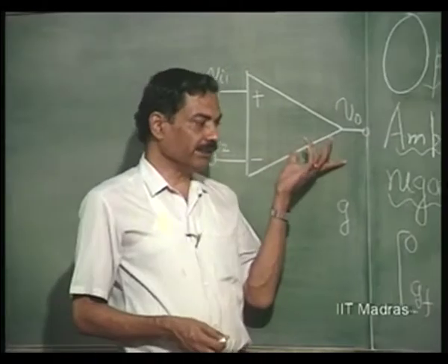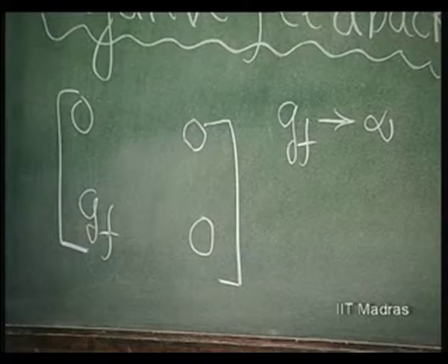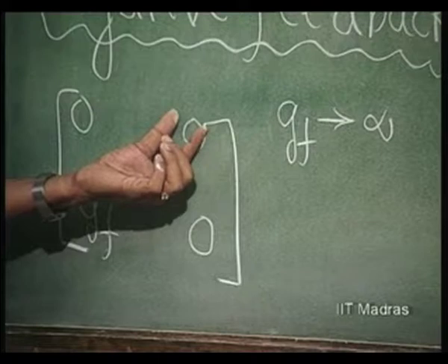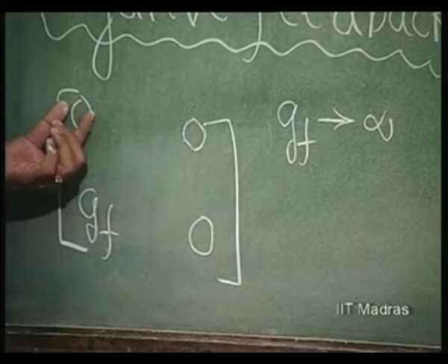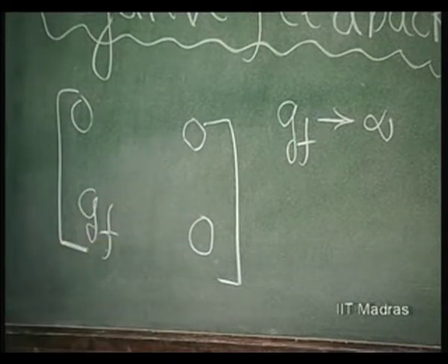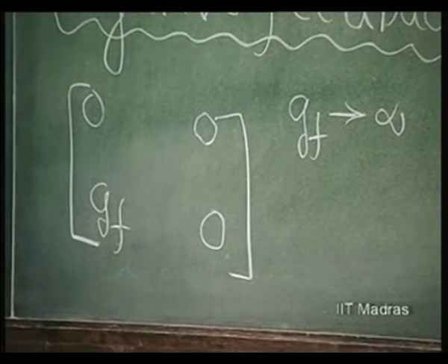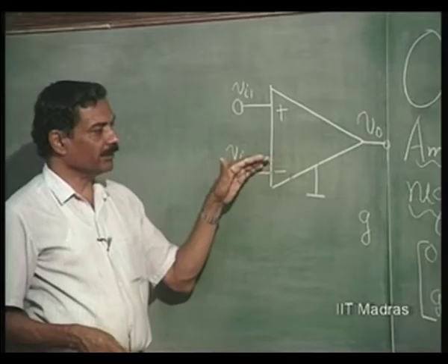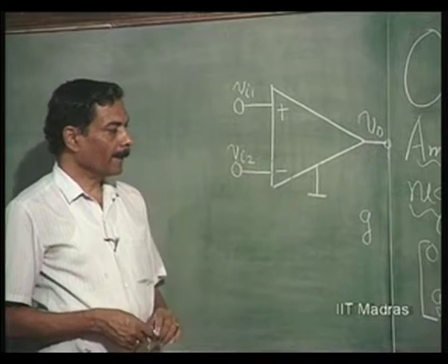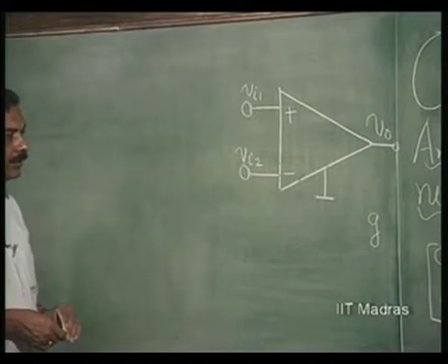So, in a cascaded version, please remember, this is the multiplication of the forward transfer parameters of the individual stages. So, it improves drastically, this keeps on coming down feedback, this is due to the input stage, this is due to the output stage. Anyway, we can design these things so that these represent operational voltage amplifier. That means input impedance is made very high, output impedance is made very low, and it is a cascaded stage. When you do that, let us see what happens.